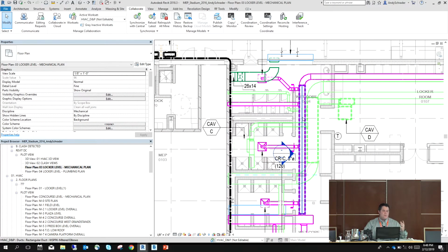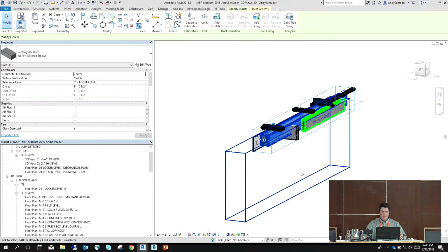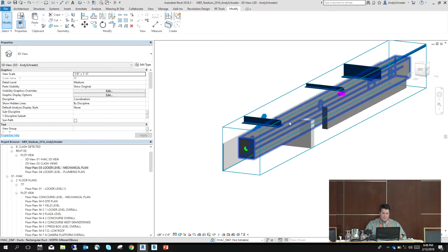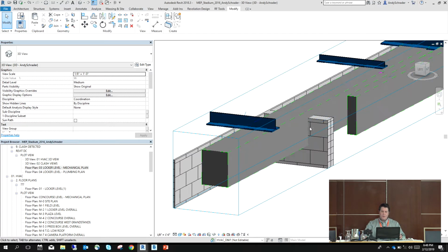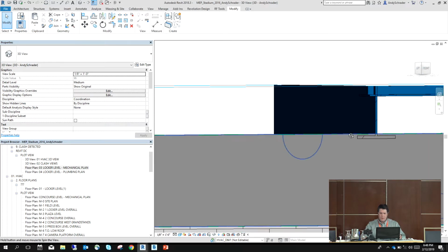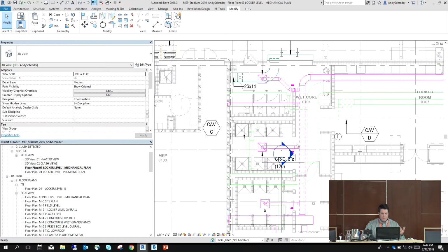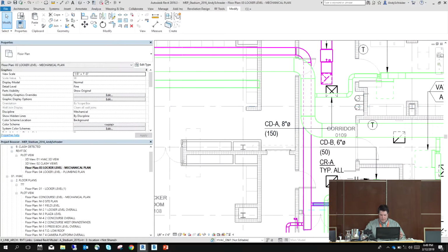One of the fun things about Revit and some of the newer features is being able to select this element, and then we have the selection box up here. So I can say, what am I clashing with? Then I now have a 3D view that is showing, and it's kind of hard to see because it's so bold, but if I turn this to thick thin, I'm running into these pieces up here. And so now I can navigate through the project by closing this out, going to another piece. I'll turn that back on so you can see it.